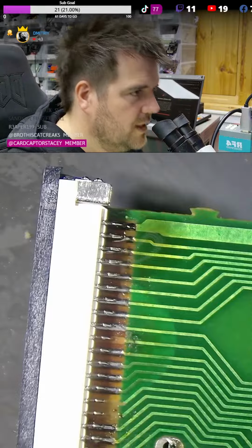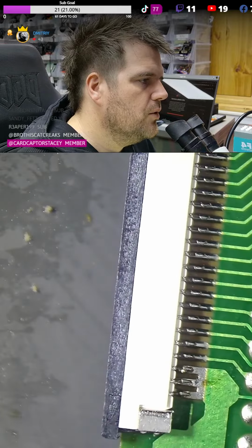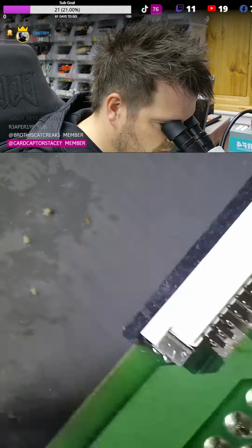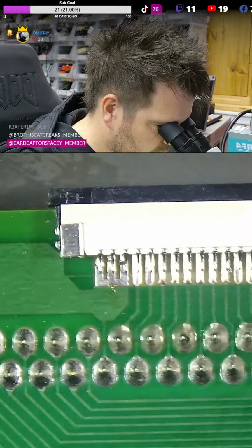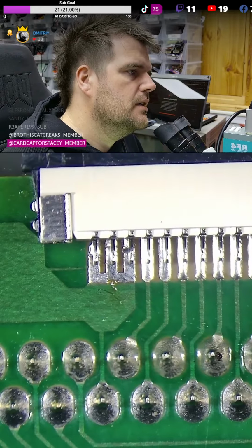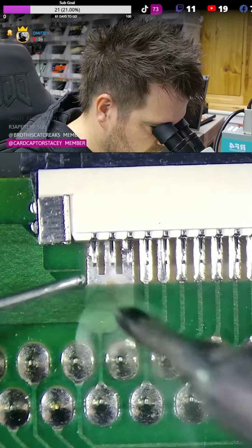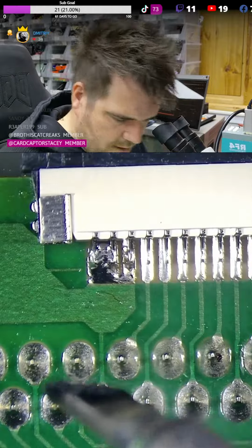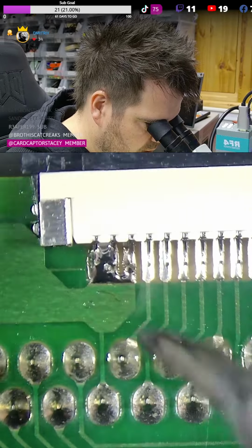And that one tacked on quite nice. So I've done a nice gentle job there. That bit's tacked on. Go all the way down. We're pretty much lined up perfectly, even right to the bottom. So that's not bad at all there. This pad we don't need to restore over here because there's 3 pads all the same. So we can flood that, get the tweezers pushed down, and that's a great anchor point.